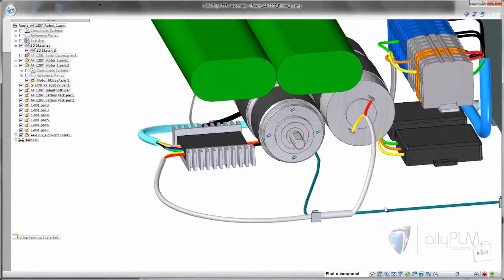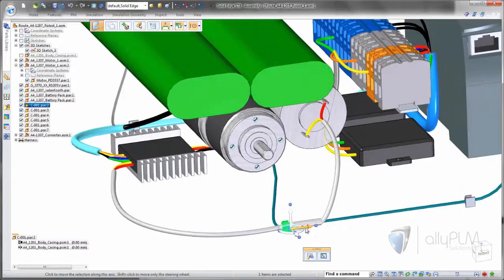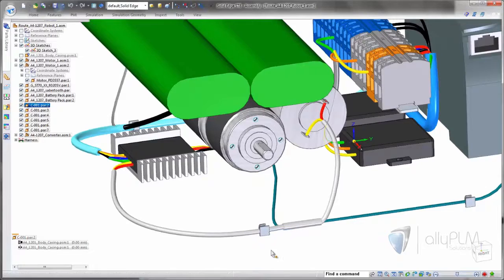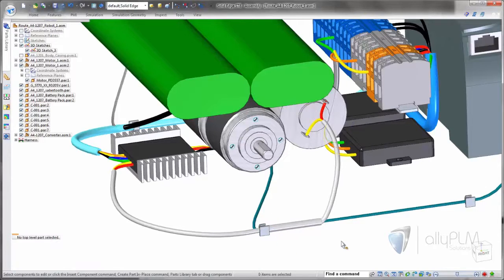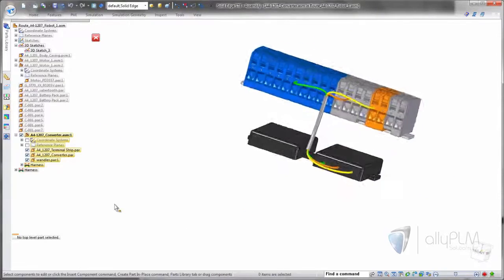Creating physical conductors gives a real 3D representation of wires and allows us to see exact sizes in an associated model. Once routed, notice that our bundle is associated to the geometry used for creation. We split the path along the clip center point.